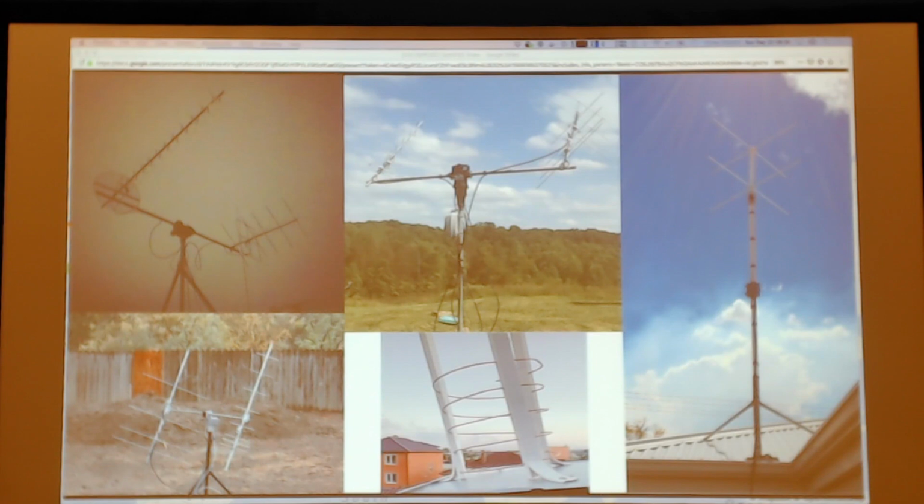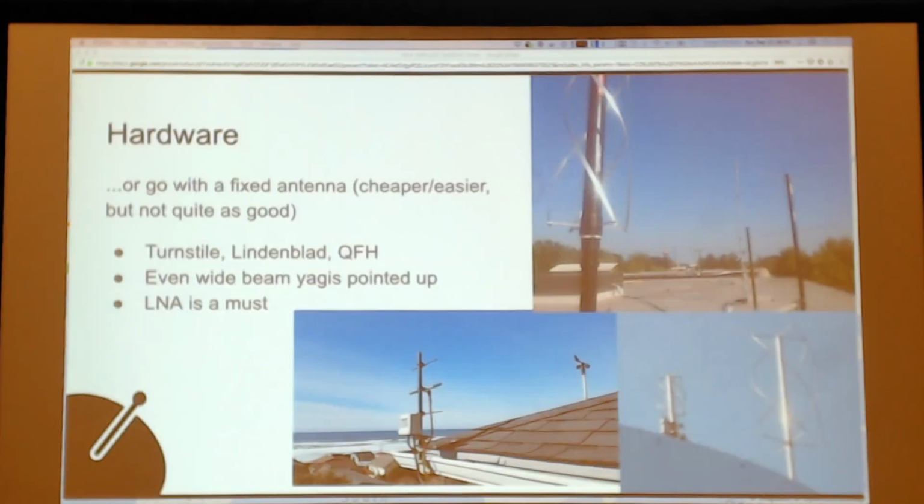I've seen people on the network who have a simple mag mount antenna on a huge ground plane of metal, and it works. It's not perfect. It's not going to be producing what you get from a high gain antenna, but in this kind of a scenario, if you can have 20% efficiency versus none, then that's 20% more than what you had before.